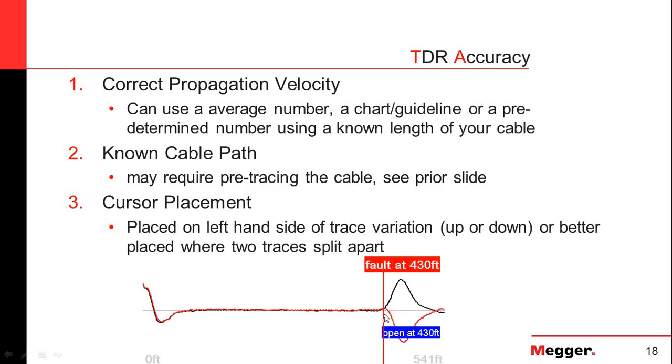Again, in cursor placement, the best would be if you had two traces that split apart, you can put the marker exactly where they split for a very accurate measurement.